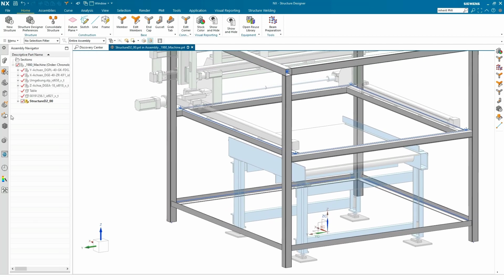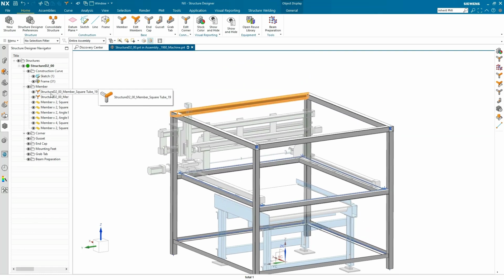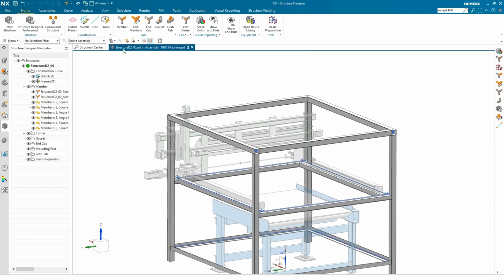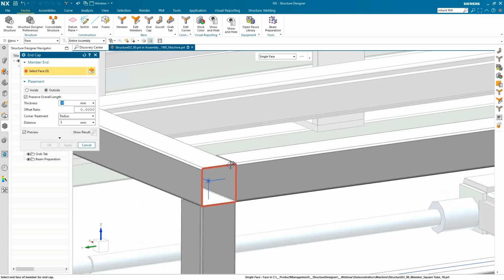As we select members in the navigator, notice how they are packed if they are geometrically identical. Should a packed member be modified with the addition of, say, a mounting hole, it will be automatically removed from the collection. A similar packing process can be used to consolidate members to create drawing cut lists.